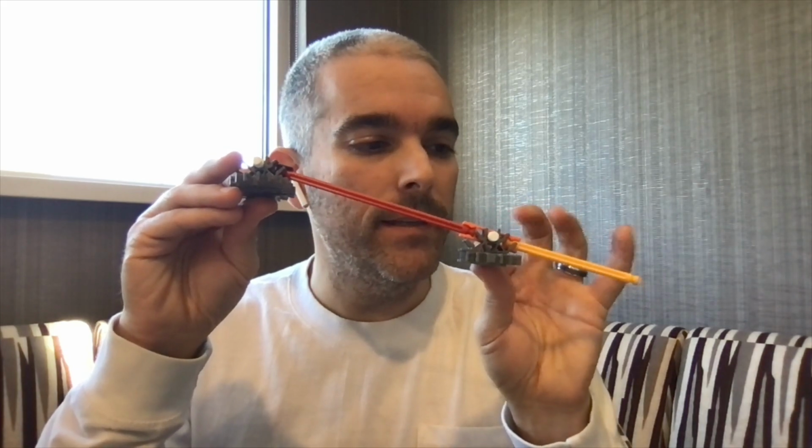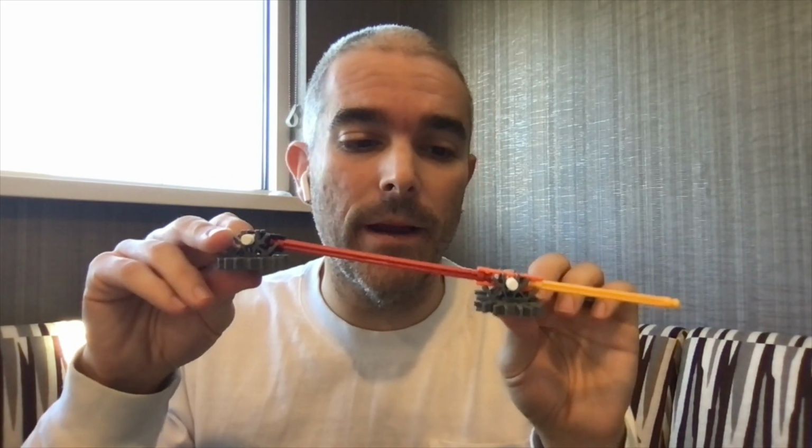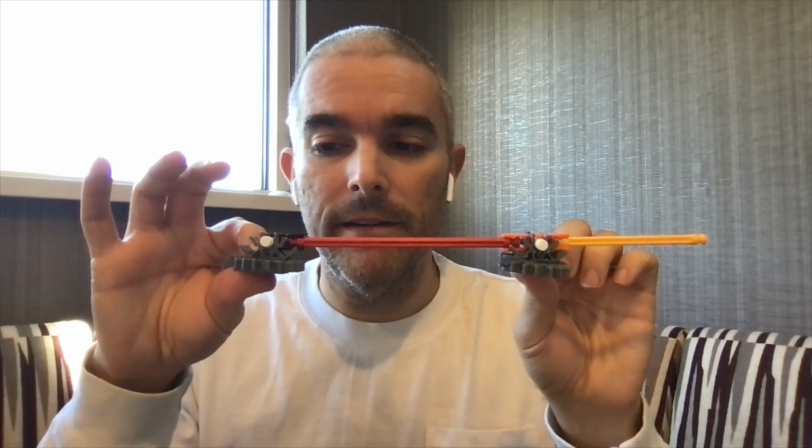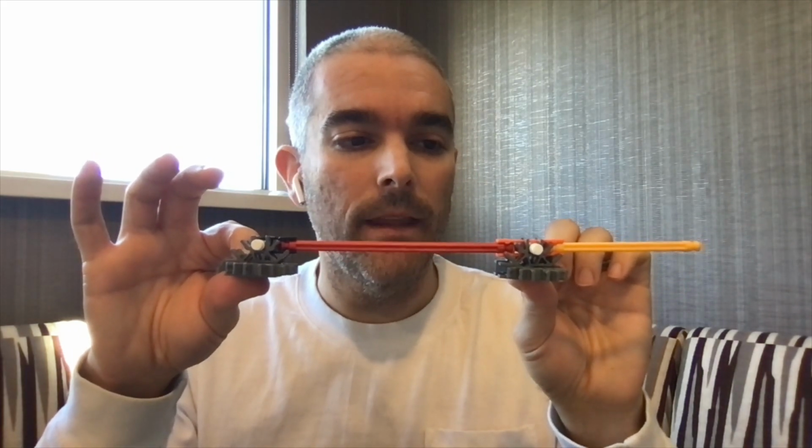When I do that, I can look at the deflected shape of the bridge. If this was up at 1, this would be 0. We can then use the geometry of the bridge to figure out that down over here would be negative 0.5. This matches our expectations from the previous example in the last video. We can also do it for point B.